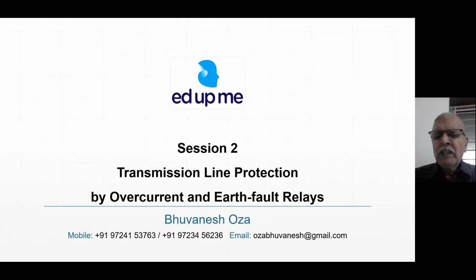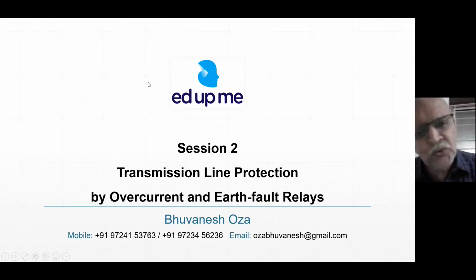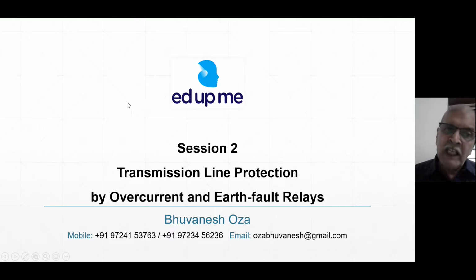The general rule is that you can spend 10% of the cost of the main equipment on protection. So for 66 kV and below, you have to use overcurrent and earth fault relays. Not only that, but beyond 66 kV, 132 kV, 220 kV, 400 kV, 765 kV, whatever you tell, you have to use overcurrent and earth fault relays as backup. So the importance of overcurrent and earth fault relays cannot be denied.